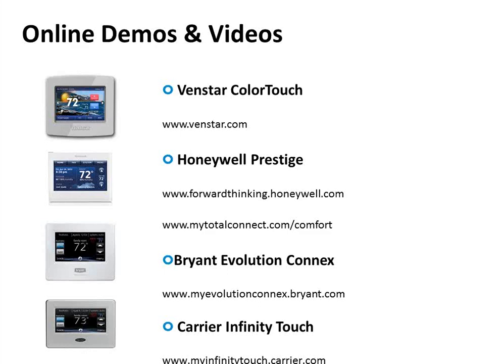The Honeywell one probably would be the best for more challenging applications, like a zoning system when you don't have a Carrier and Bryant furnace. The Honeywell will be the best one there because they actually have a zoning system compatible with these wireless stats, whereas Ventstar doesn't. So they all kind of have their various niches.